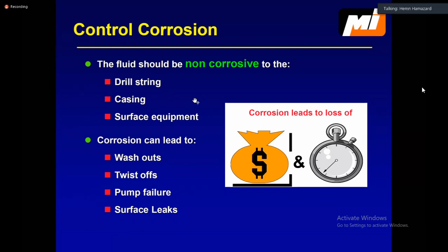If you don't do that, if you have a lot of corrosion in your mud or downhole, it can cause a washout. A washout means you have a big hole or fracture in your downhole equipment, either the drill pipes or the other BHA components. It can cause a twist-off of the connection. Any connection on the threads can fall off without proper corrosion inhibition. Mud pumps, because they are all mechanical equipment, steel or iron or whatsoever, can also be impacted by corrosion.